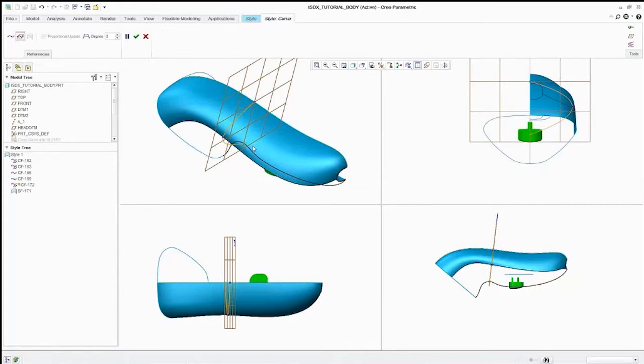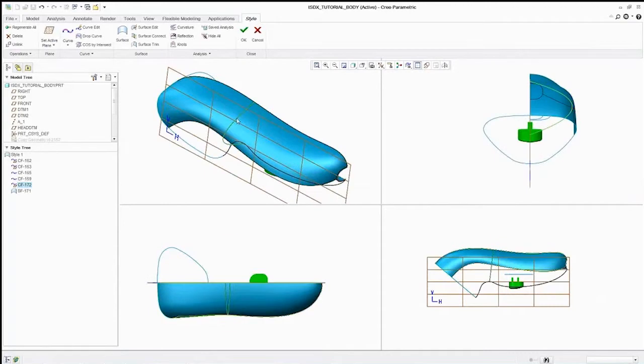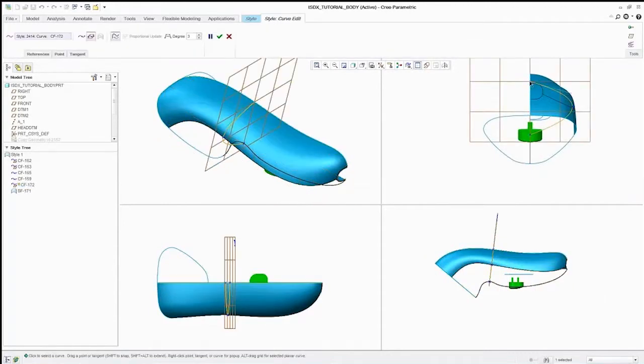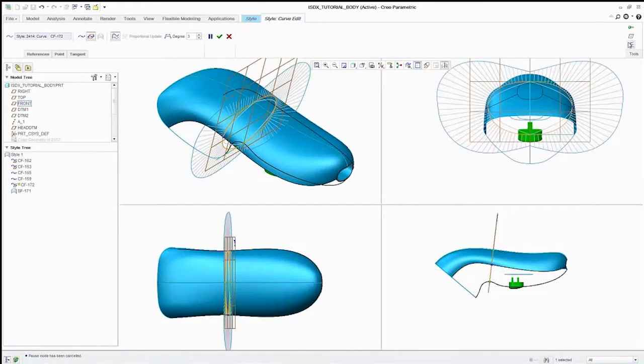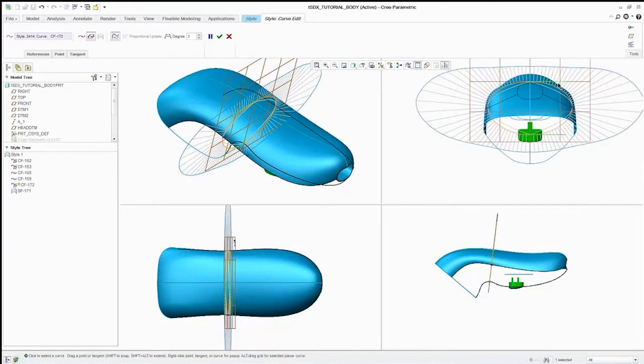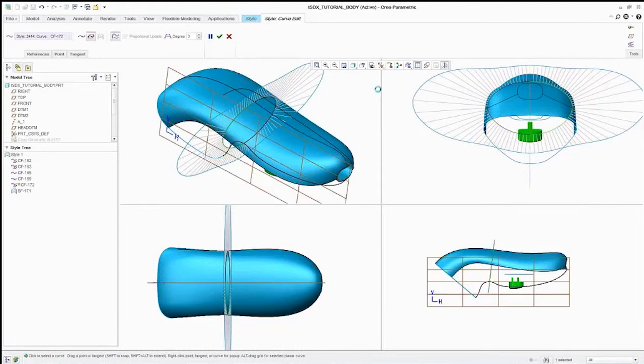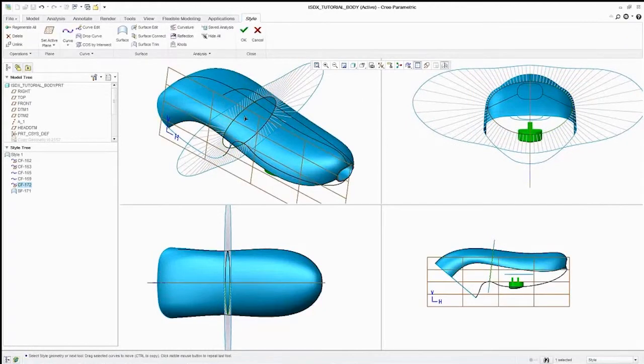Now at this point, we're just throwing in some additional curves to drive our surface, and we can lock those curves to a certain plane very quickly. Again, utilizing that 4-panel view to build these curves out extremely quickly. We can mirror that general curve across the middle plane or whichever plane we set this up, just finish out a curve and have that also drive a surface in the other direction as well. Make sure that we have a good symmetric shape going on here.